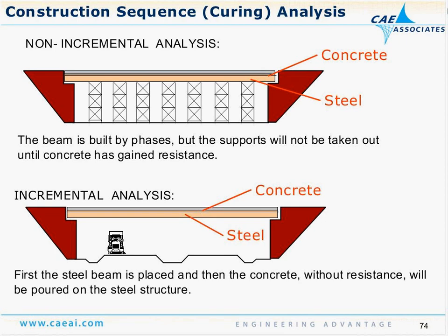So if we're going to model this bridge right here with beam elements and the actual construction processes to construct the steel bridge without any underlying supports and then pour the concrete on top, the stress state is quite different with that condition than it would be if it was fully supported, such that basically the steel and concrete both came alive in a stress-free condition.